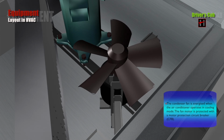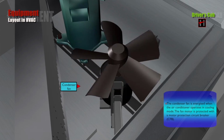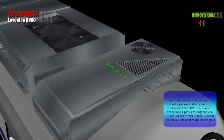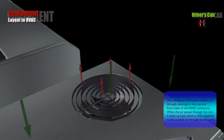The condenser fan is energized when the air conditioner operates in cooling mode. The fan motor is protected with a motor protection circuit breaker (CFB). If the condenser fan stops to operate in cooling mode, the HVAC controller will shut down the refrigeration circuit and no cooling will be available. The condenser fan draws ambient air through openings in the top and front sides of the HVAC enclosure. When the air passes through the coil, it picks up heat, which is then expelled to the outside air through the fan grill.